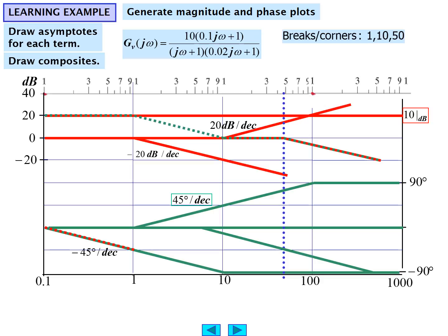Same thing with the phase angles. We're going to start off with minus 45 degrees per decade, so the dotted red line is going to follow that. Where it goes to 1, it's now going to get support from the plus 45 degrees per decade, so it's not going to get any more negative as a phase angle, but it's going to stay horizontal until it hits the next asymptotic break, which is down around 7 radians per second or so, which is an additional negative 45 degrees per decade. So it'll go down slightly.